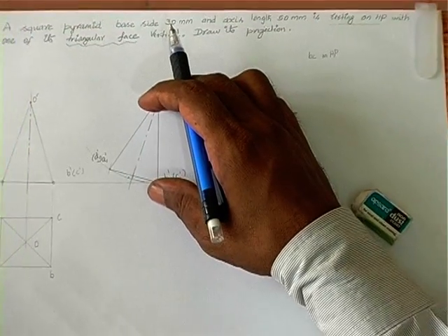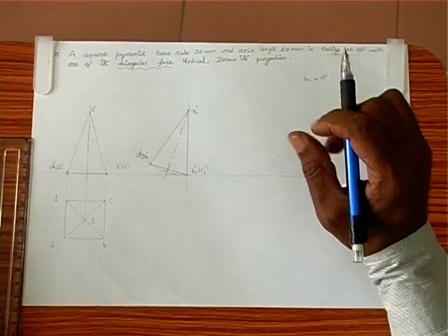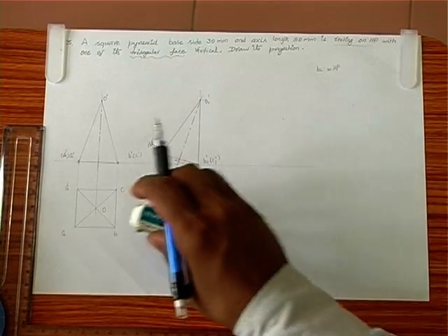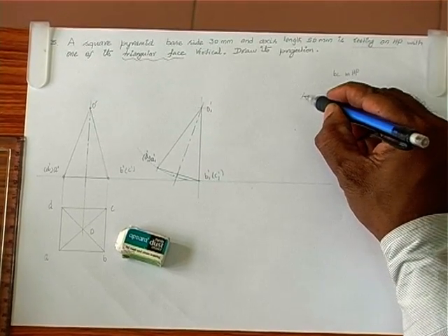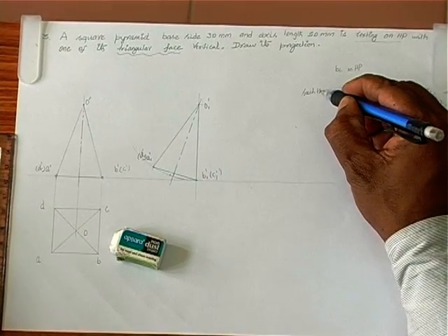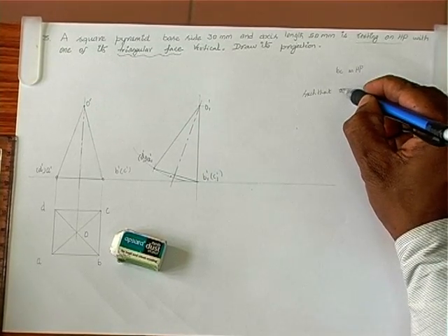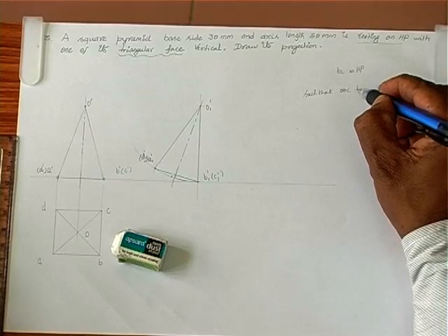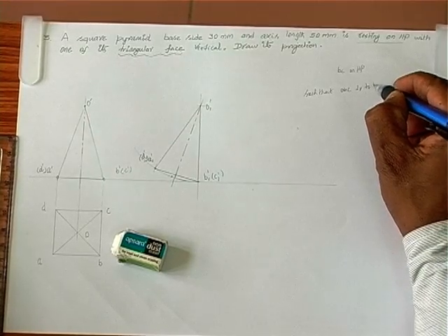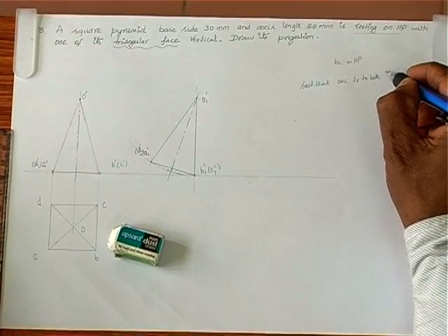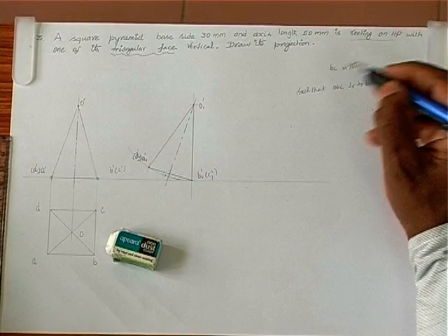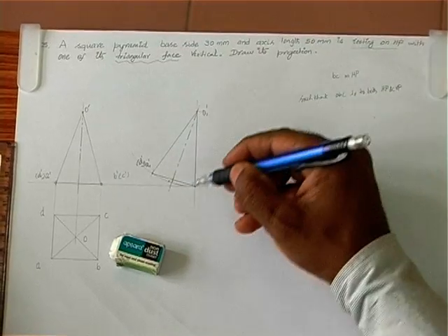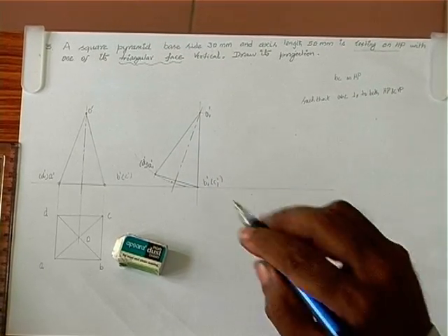This can be read in another way, as BC on HP such that OBC is perpendicular to both HP and VP. BC is a line in front view, it is still a line in top view as well.